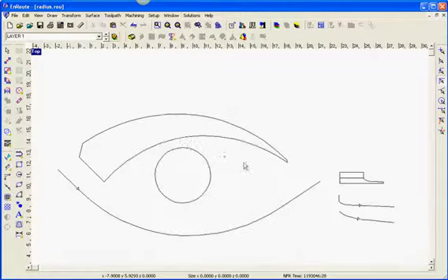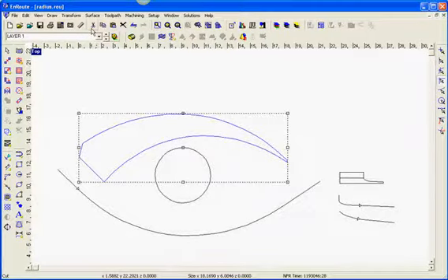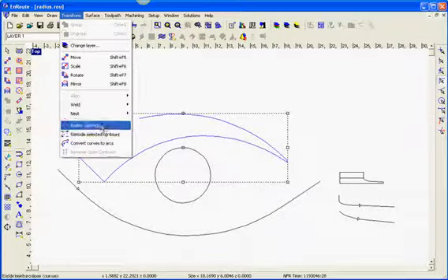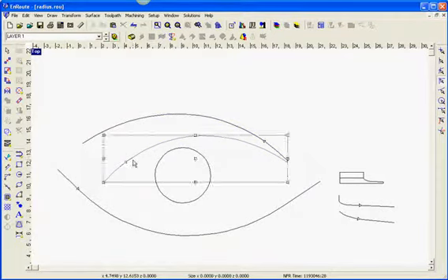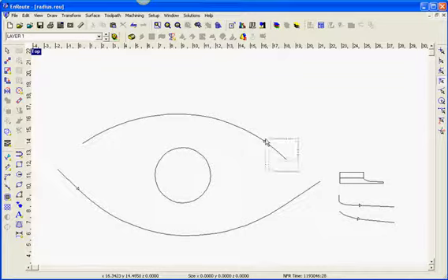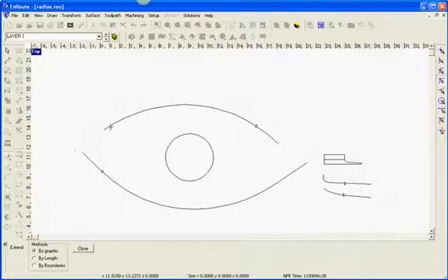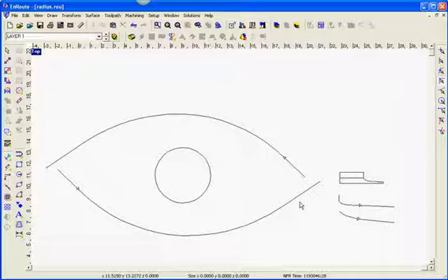All right, so there's my one part, and we're going to do it across this back shape here. So we're going to come here and go to transform, explode, delete that, delete that, delete that one, and we'll go back to extrude here and just continue these pieces a little bit. Okay, so these become the lines that we're going to extrude on.